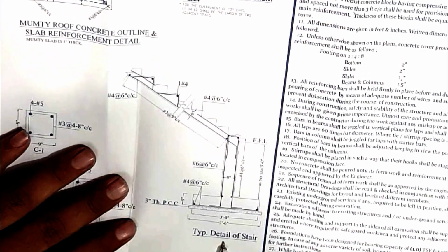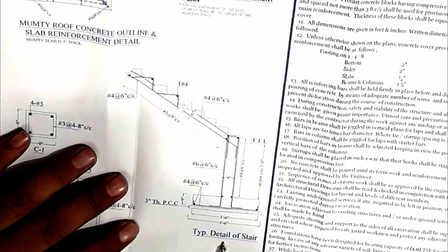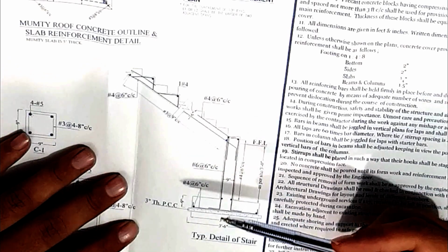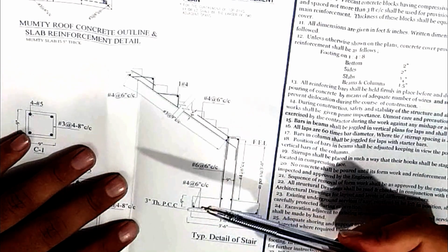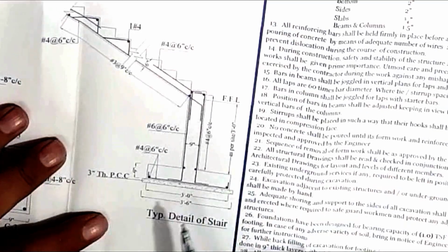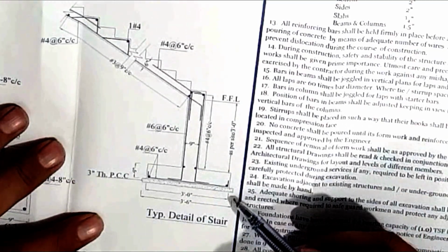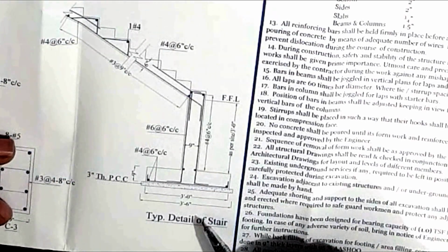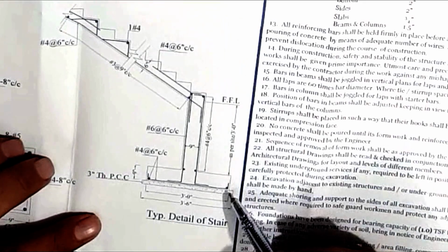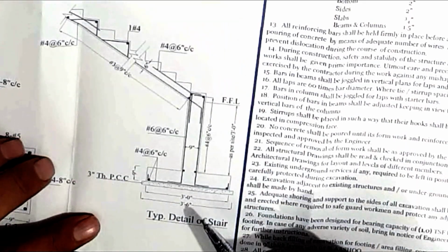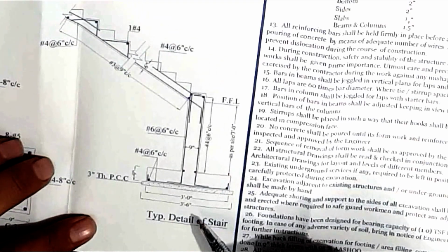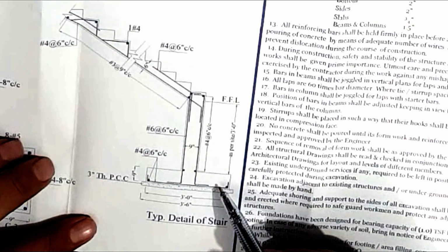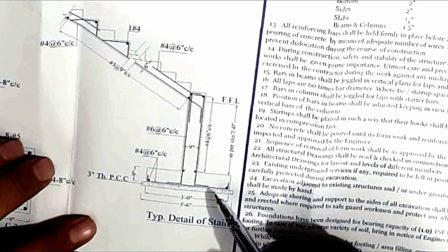Okay, so how will you discuss it or how will you detail it on site? This is one of the tricky things that is found at any construction site. Okay, so the first thing, that is the foundation. Before the foundation we have used PCC of 3.5 feet, and we are using 3.5 feet because the foundation size is 3 feet. Now what happens at our construction sites, basically we miss this foundation during our foundation construction process for any stair, and that is where we cause the problem.